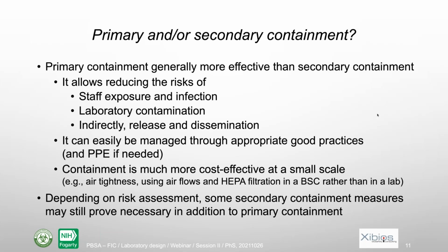One thing we need to remember also, and that's quite general, is that containment is much more cost effective at a small scale. A biosafety cabinet, for instance, treats air. There is an airflow, there is a HEPA filter, and because of the small volume of air, because of the small dimensions of the HEPA filters, it's much less costly than having the same type of airflow or a filter at the level of the whole room, for instance. So working at small scale is almost always more cost effective than at a larger scale.